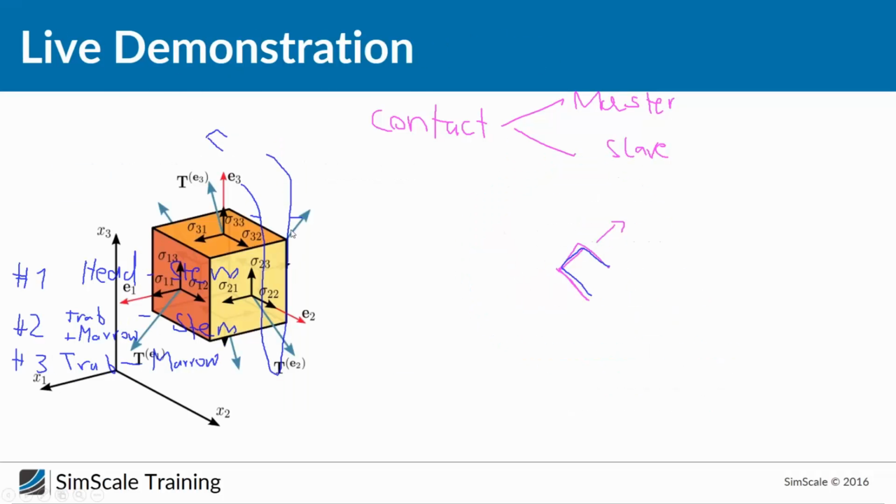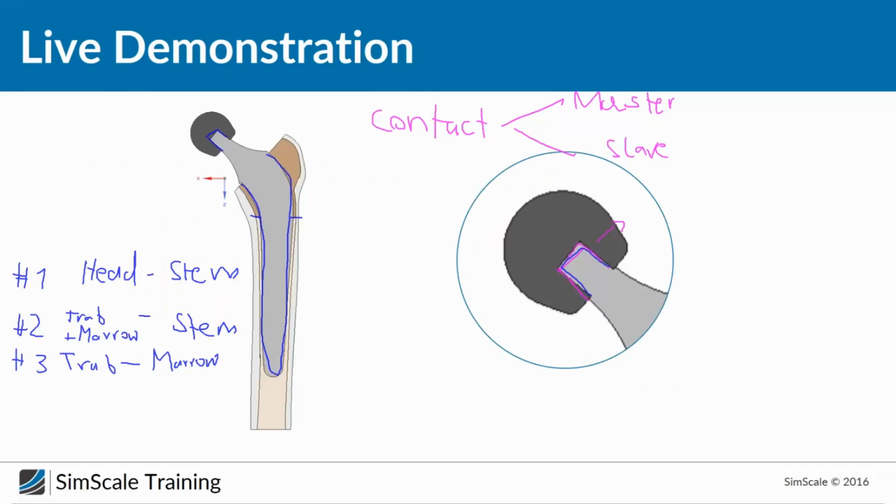So we have a last contact here at the outside. Oh no, it became a little bit chaotic. But I hope you basically got it. And we need now to define this contact, as I mentioned, because otherwise the solver or the simulation tool does not know how these parts are interacting. And that is what we will do right now.